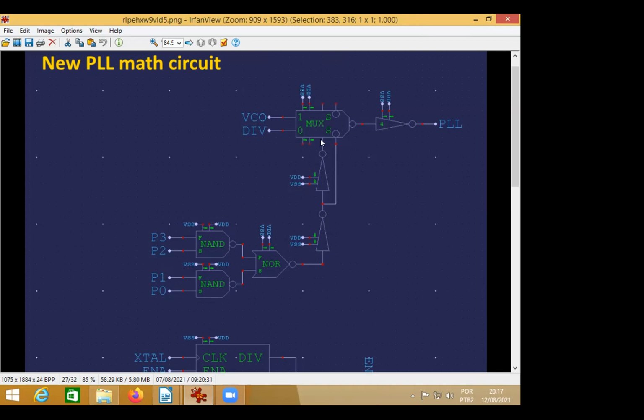So during the whole time it takes for the control signals to get there, the VCO signal is supposed to bring the output down and upset the output of the div, which perhaps is going up at the same time. So you have a glitch at the output.